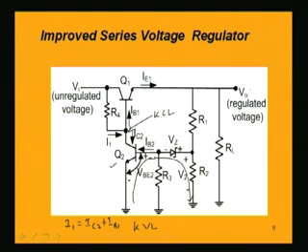So this voltage regulator is maintaining the output voltage V0 at the same value. We have seen that when V0 increases, it is pulled down again. That means it will be brought back to its original value. Similarly, you can think about the other way: when V0 is decreased, you will find that it will finally be increased again and maintained at the same value.